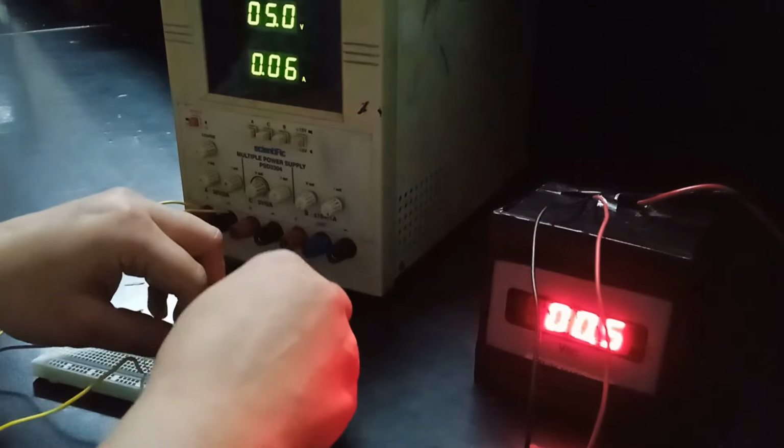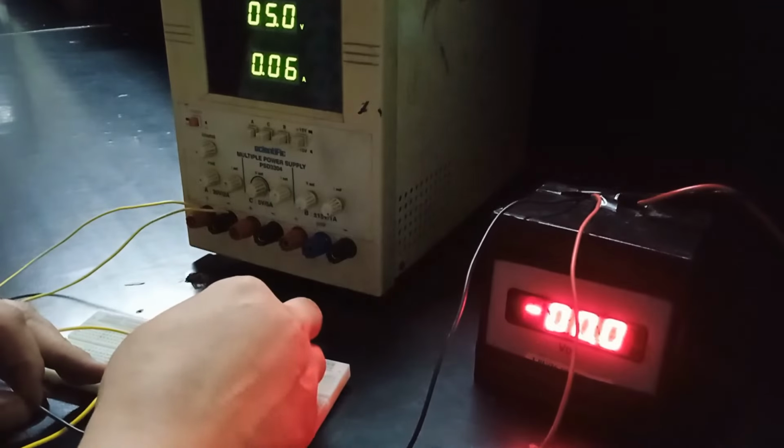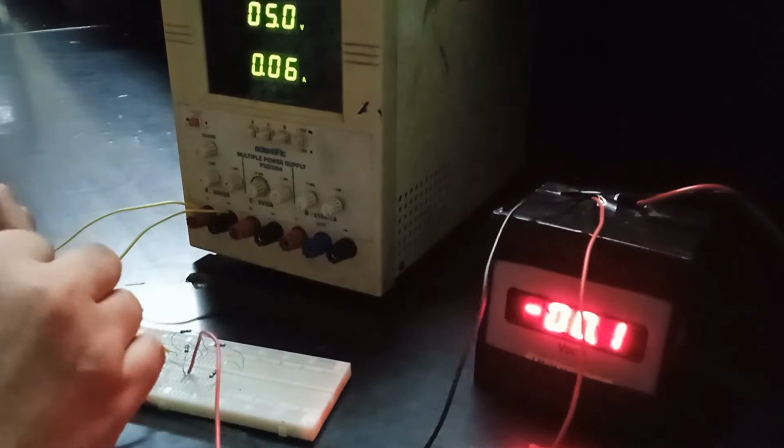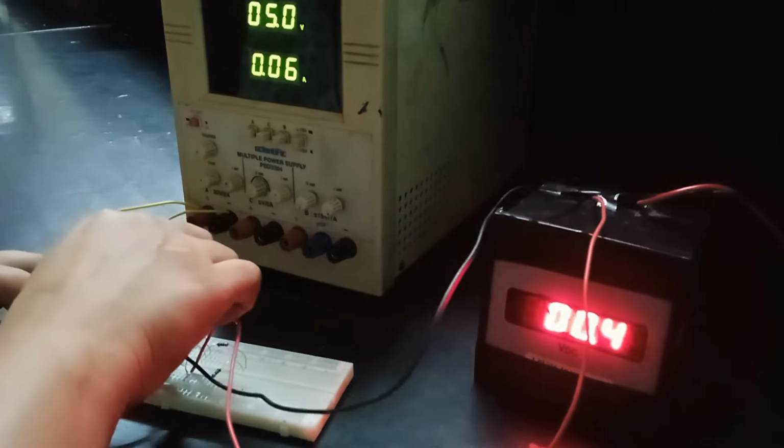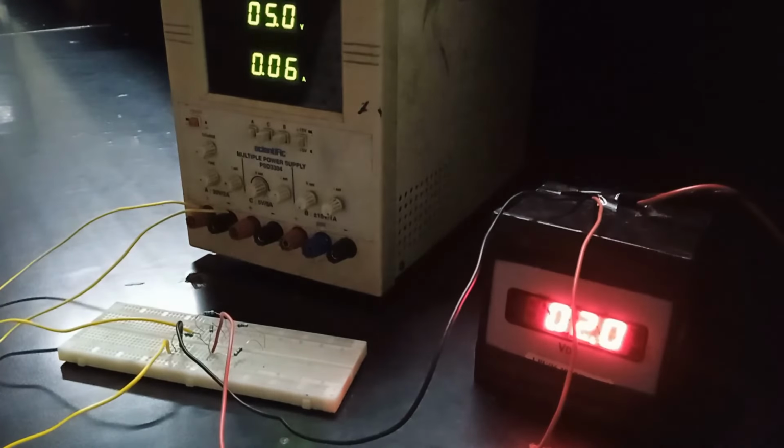And finally V5. So V5 is nothing but the voltage across R5. So that comes out to be equal to 2 volt. By inserting these values in our KVL equations, that is loop number 1, loop number 2, and inserting the values, you will be able to verify left hand side is equal to right hand side.